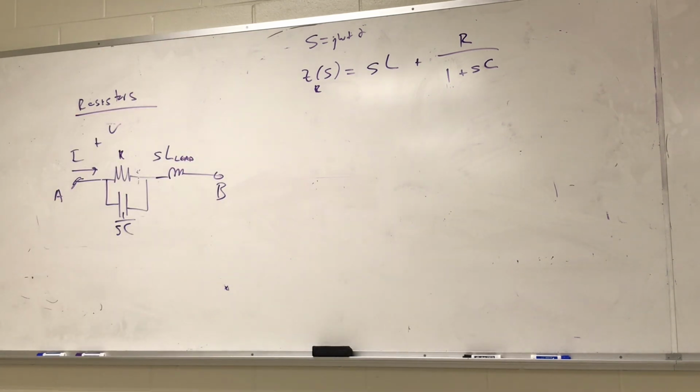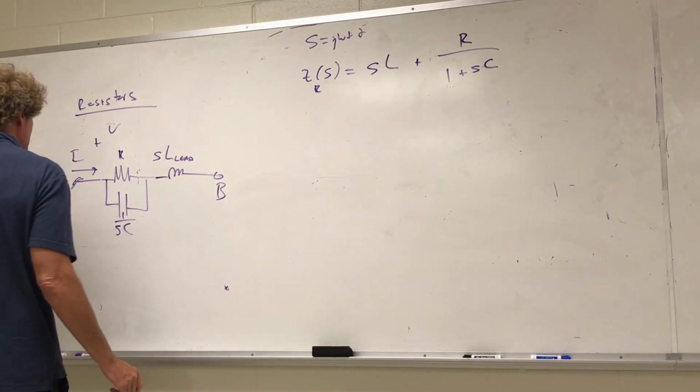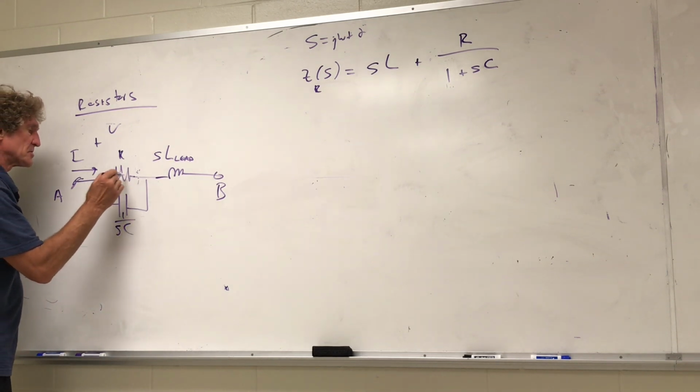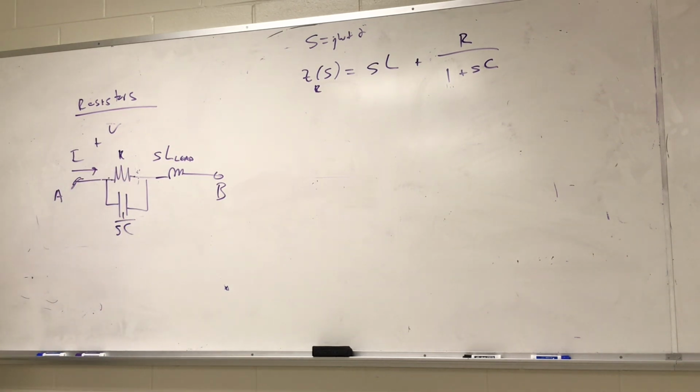So in his book, at the bottom of page 508, that type of a circuit, but he does one thing. He calls it L sub L is lead and L sub X is internal. Almost always, any internal inductance associated with this resistor is negligible. So you can chop off that L sub X.